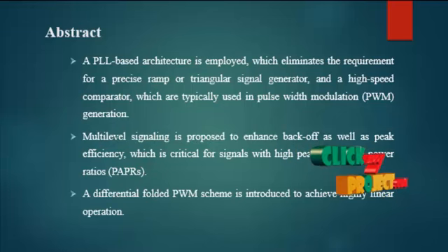A PLL based architecture is employed, which eliminates the requirement for a precise ramp or triangular signal generator and a high speed comparator, which are typically used in pulse width modulation generation.